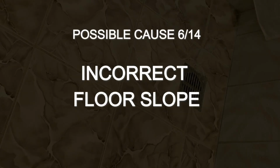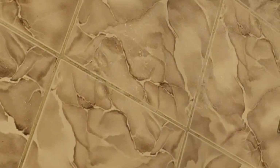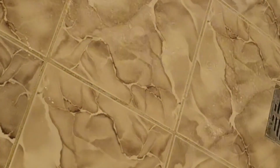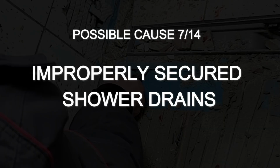The sixth version, flow slope. In the shower area, water should flow towards the drains, but in other parts of the floor, there was no slope, and in some places, the water even flowed in the opposite direction towards the walls. Because of this, water stayed on the floor longer and seeped into the seams. This increased the load on all the leaky areas, but it still didn't explain the water leakage through the waterproofing on its own.